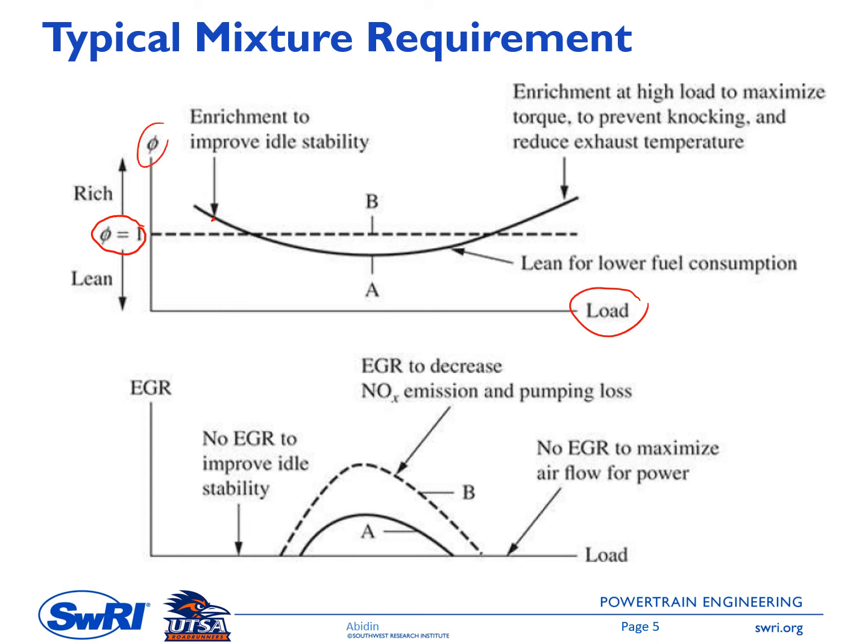And then A here, as I mentioned to you, is designed for optimization of maximum torque, part load efficiency, and idle stability. So for the idle condition, its load is almost zero. In this case, we need to have a slightly rich mixture to improve idle stability. And then in chapter 6, we also take a look at the requirement to have stable combustion at the idle point, which is a minimum valve overlap. And the purpose of having this minimum valve overlap is to minimize the residual inside the cylinder chamber.